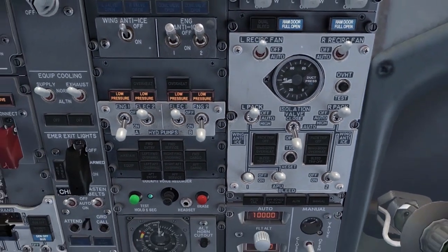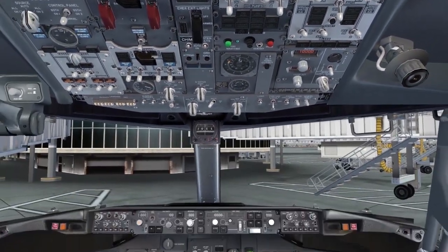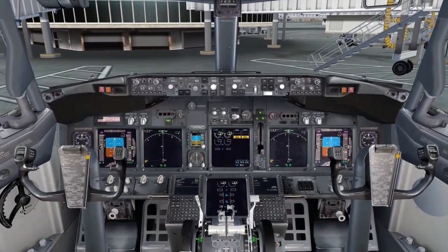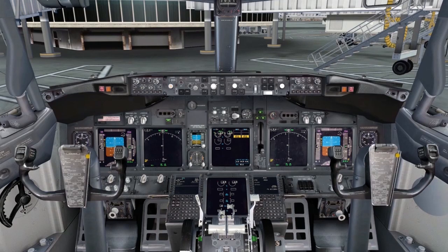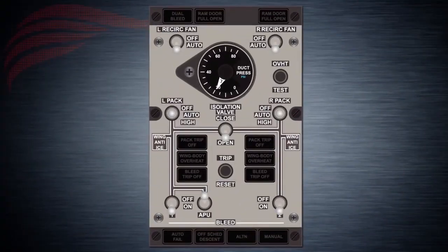air shutoff valve. Bleed air temperature is cooled in a cross-flow heat exchanger referred to as the pre-cooler. Ideal bleed air temperature should be between 199 degrees Celsius and 229 degrees Celsius, and it is achieved by exchanging heat between cool engine fan air and bleed air. An over-temperature mechanism protects the pneumatic manifold from receiving bleed air that is too hot. The threshold temperature is 254 degrees Celsius,